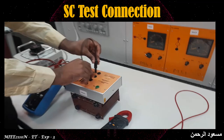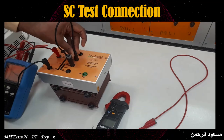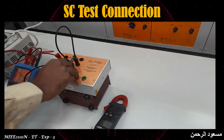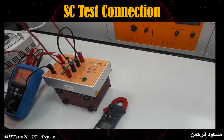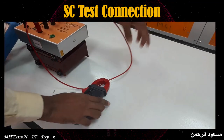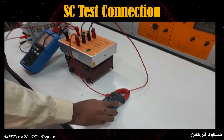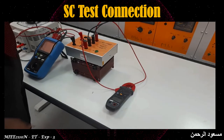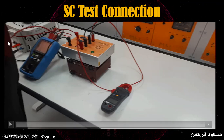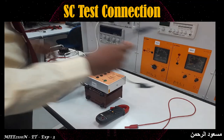See, first the secondary coil is short circuit series connected. The two individual secondary coils are serially connected, and single wire is connected between the 220 volt point and the 0 point, and the clamp meter is connected along the wire. Okay, so this is how the connection for short circuit test. Now we will go into the conduction and tabulation of open circuit test.